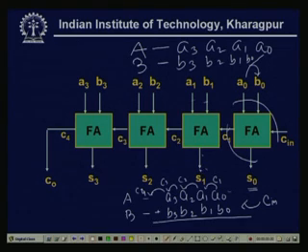S1 is the second bit sum, and C2 is the second carry bit. Similarly, it is fed to the third full adder module, with A2, B2 as input and S2 and C3 as outputs, and for the fourth, A3 and B3 are the operands, and S3 and the final carry, which we are calling CO.